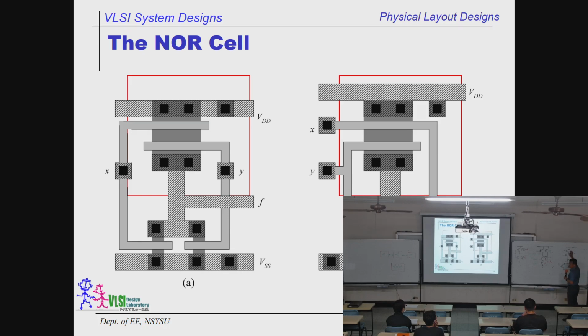But the problem here is we have cascaded the PMOS. This is R, this is R. We would like to bring it down to become 2. So the overall sinking capability is the R, identical to the original one. So we would like to reduce the resistance of each MOS. So the size must be increased by double.